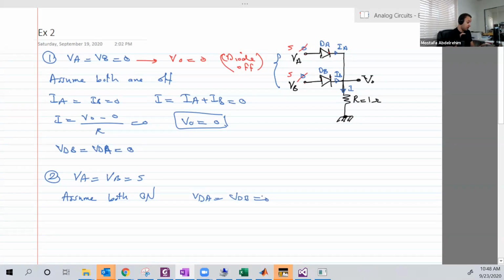We are still, I'm sorry, let's do it with practical models. That's better. I just gave you the harder one, the easier way, which is solving using the ideal model. But I will do all the examples from now on using the practical model, or the constant voltage model. And in the exam, or the assignment, or even in practical life, you should use the constant voltage model. But if I want you to use another model, I will tell you explicitly in the exam or the homework.